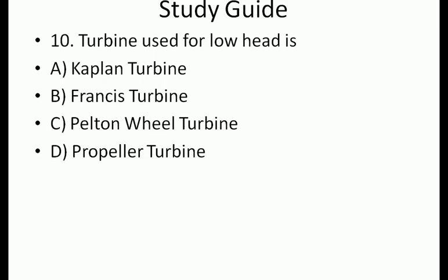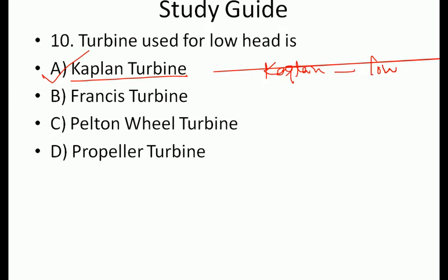Turbine used for low head is the Kaplan turbine. You know the Kaplan is for a low head, Francis for medium head, and Pelton for high head.